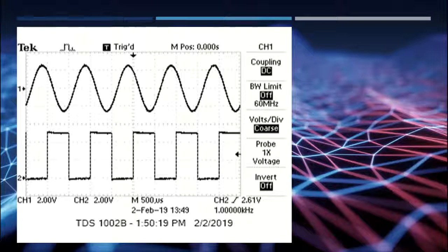If you remember correctly, my frequency was set at 1 kilohertz for the channel 1 signal. What that means is that for every cycle I get here, I should get a cycle up here. And you'll notice that it all matches up.